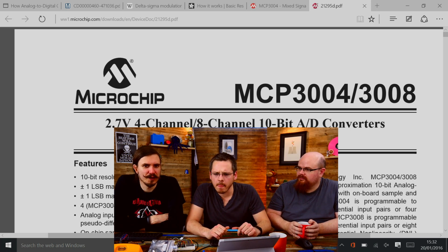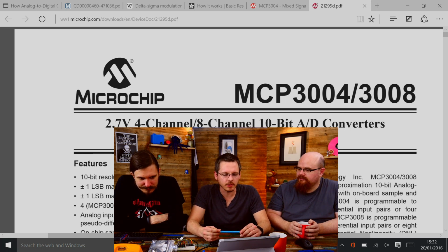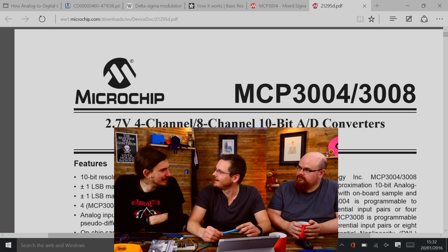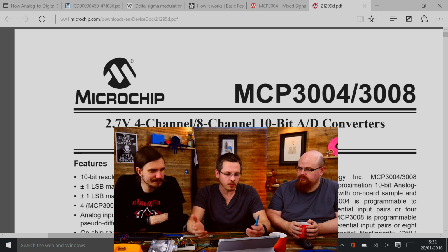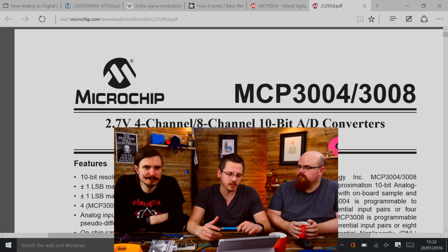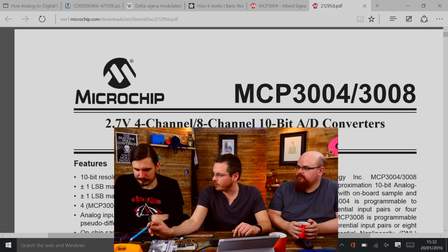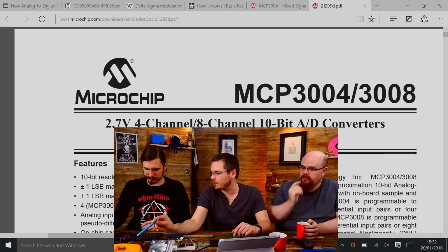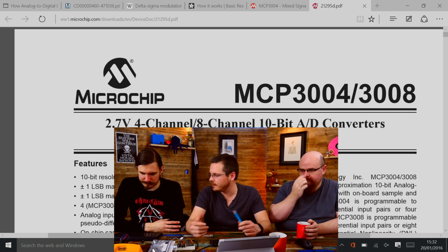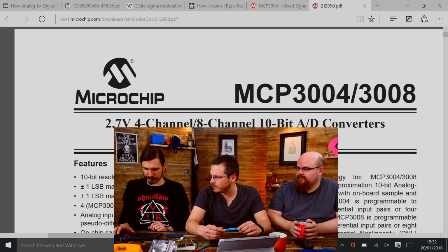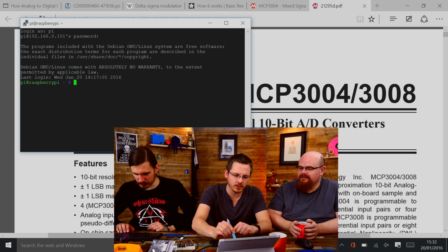Datasheets can be very, very scary. I think most of the time you've got to know what to ignore, or what bits matter to you, basically. But for most uses that we'd use, this would be perfectly appropriate, and it would be easy to set up and easy to talk to. On the Explorer HAT, we've got the ADS1015, which is a really nice ADC, and obviously we've got all the code libraries for that there. I think you've got an LDR hooked up there, Phil. I have. It works quite nicely.